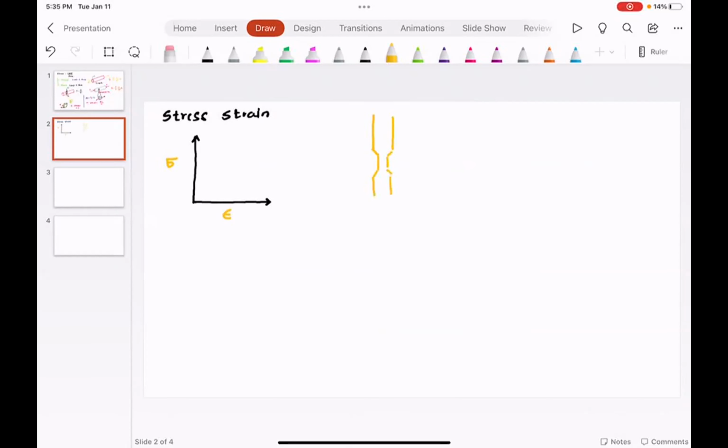And when I was in grad school, doing an experiment like this was fun. But what we used to do is we had to use something called an extensometer, a gauge that you attach, and basically you see the deflection of the gauge. But now you can do a displacement measurement, or a stress strain curve, using an iPhone or iPad. You can set up the optical markers and then, just like it tells you the height of a person, it will give you the deflection that is changing with respect to time.